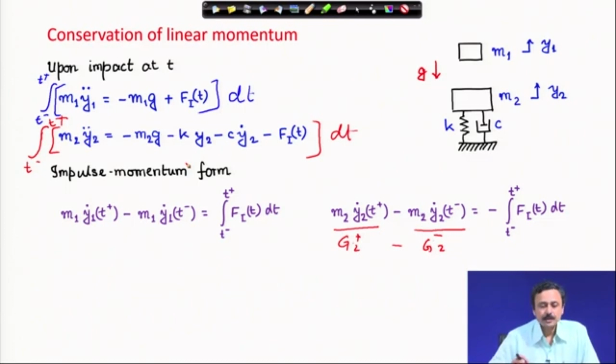In that very short duration when the impulsive force acts, the mass m2 will hardly be able to move, therefore y2 hardly changes, and there will be hardly any contribution of the spring force in momentum change. That force will hardly contribute in that short duration.